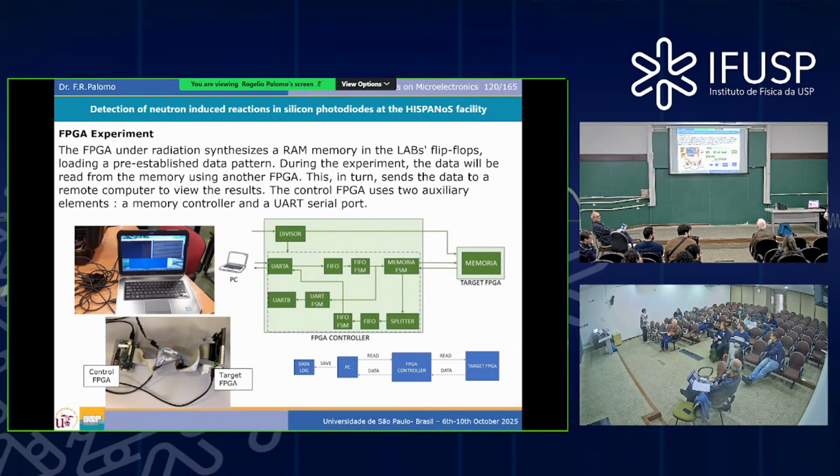It was an exercise of doing things in an FPGA you typically don't do. Typically, you don't use an FPGA as a memory. But in our case, we were interested in knowing the behavior of the flip-flops in that FPGA, because at the end, we were testing the technology. But remember, in that FPGA, we have static RAMs built in, and we have flip-flop resources that you can route as a RAM matrix.